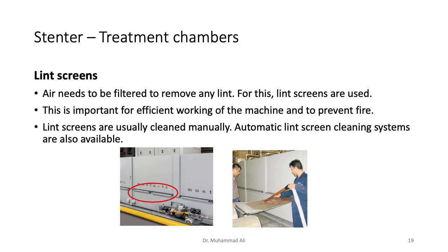Now, what should be the frequency of cleaning of these lint screens? Well, that again depends on the fabric that you are processing. Usually, for a normal woven fabric, let's say, you might require cleaning after every 2 or 3 days, or maybe even before that if the fabric that you are processing creates a lot of lint. So it's one of the jobs that the operators have to do all the time, that they inspect the lint screens frequently and clean them as and when required.